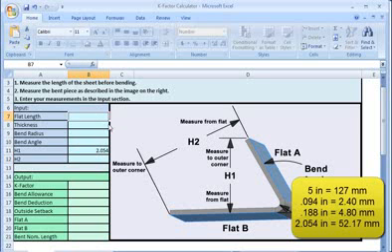The flat length is 5 inches because we started with a 5-inch plate, so enter it. The thickness is 94 thousandths of an inch. The bend radius is twice the thickness, so it's 188 thousandths of an inch. And the bend angle is 110 degrees.